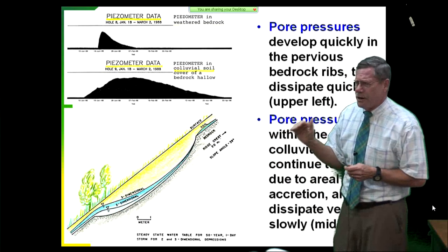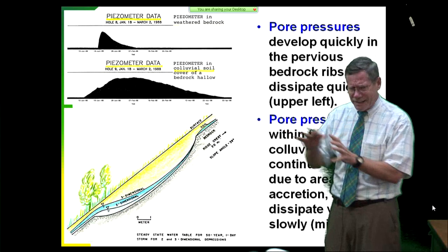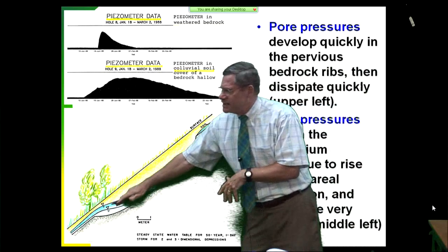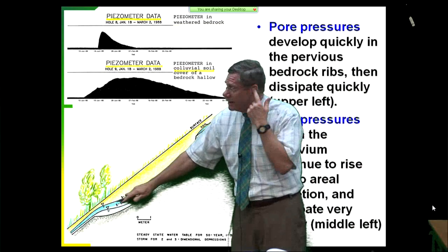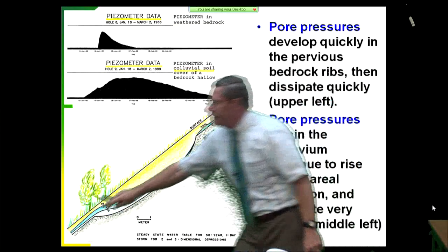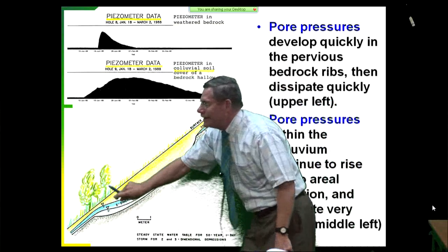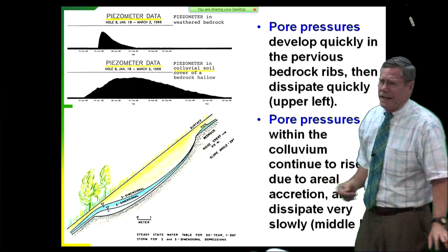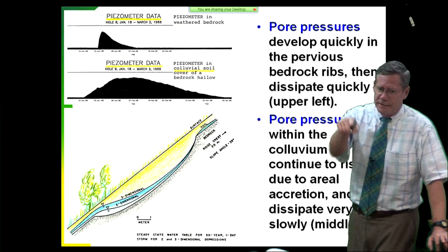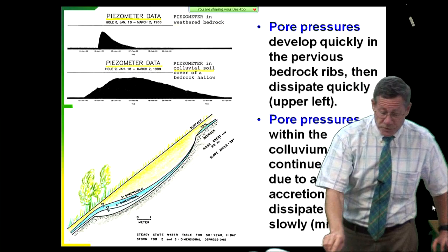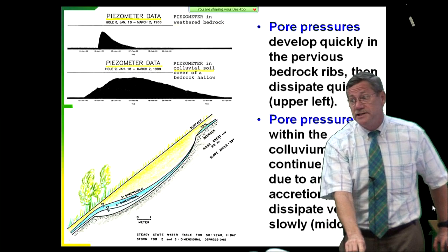But finite elements are good for seeing stress concentrations, strain concentrations, seepage concentrations. They're telling you, here's where I need the subdrainage. I don't need it up here. I don't need it down there. I need it right there. That's where I need the subdrainage. And that saves my client a lot of money. If I can say, right there's the sweet spot. Put it in right there. Don't you wish you could do that all the time? Now, that's a lot easier said than done.